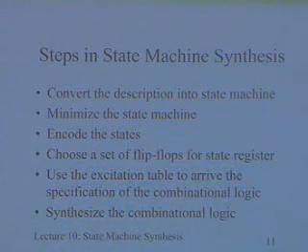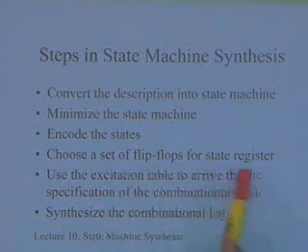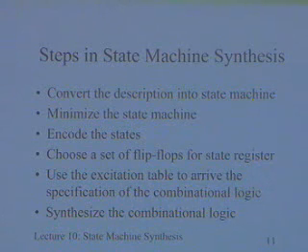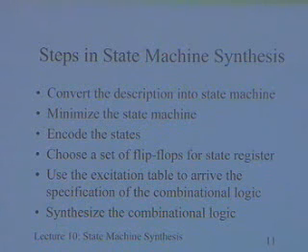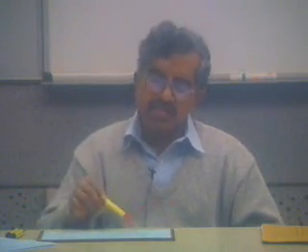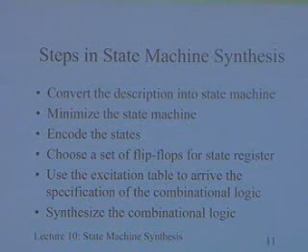Choose a set of flip-flops for the state register. I have to decide which type of flip-flops I am going to use for implementing the state register, and of course it is not necessary that I have to use the same type of flip-flops. There may be a few problems, we will talk about those later, where maybe at one place a set of T flip-flops is better, and for some other places D flip-flops is better. Typically, when you are choosing a set of flip-flops, unless you can find out something very specific in the problem, the simplest thing is to go ahead with the D flip-flops, because in the case of D flip-flops this particular step gets avoided.